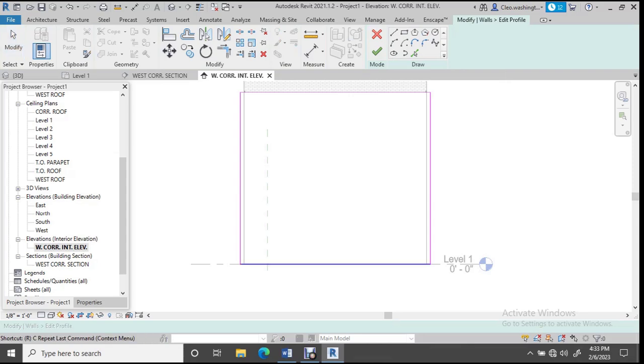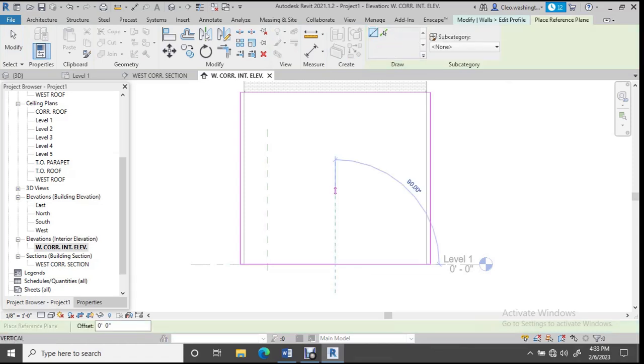So you want to start off by drawing reference planes. So you go RP, and let's draw a reference plane, okay? And then let's hit RP again, or while it's active, let's give it an offset of, let's just say 3 foot. We'll create a 6 foot opening. So you want to offset this guy 3 foot, or let's give it an offset of 4 foot. I'll let you determine. I'm going to draw mine in at 4 feet.